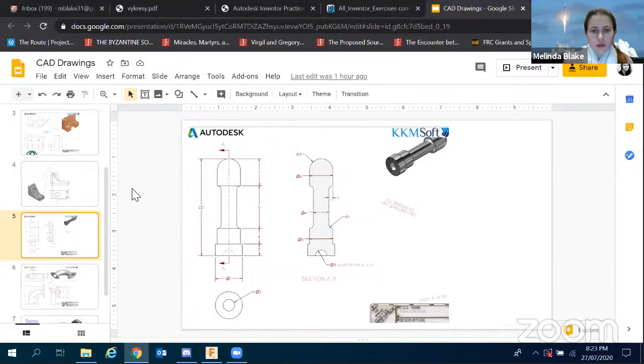So you make a sketch for the right-hand side of it, and then we're going to revolve that shape around in order to make the full body. This one can pretty much be done in a single step. What I am going to do, just to make my life easier, is not put the radiuses, those 2 little R1s, into the sketch. Instead, I'm going to use the Fillet tool once I'm in the 3D shape. It just makes it a bit easier to do the sketch. Okay, so hopefully that was enough time to grab a screenshot of that.